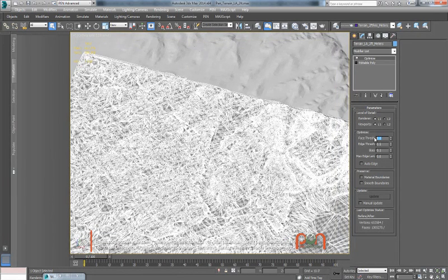And let's take this face threshold down to 0.5 as well. Or we could just get rid of it entirely and turn it off completely. Sticking it down to the surface at that point would be very slow. So this might work a little bit better for the detail along the edges of the river that we want to have fairly accurate.